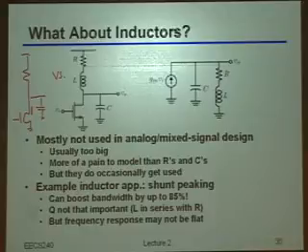Okay? So the way this works is actually kind of interesting. Roughly speaking, to understand this, the way you should think about bandwidth is that bandwidth is really about how fast you can move charge in and out of a capacitor, right? Well, if you think about this structure here, let's say I put some step signal into the gate right there.